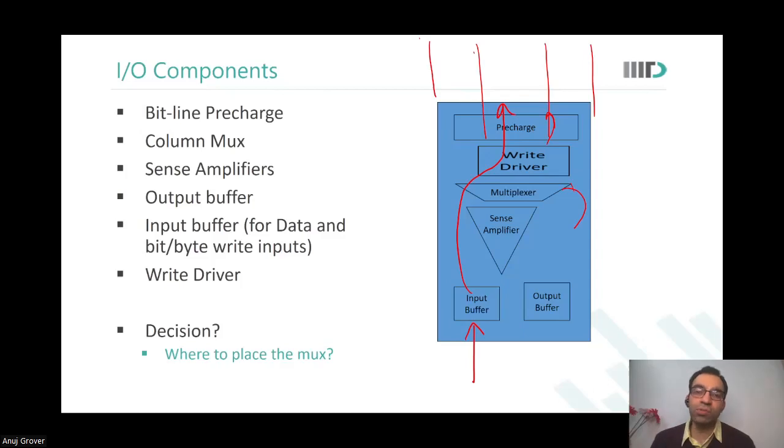So if the time to discharge the bit line to 0 has increased, what has increased? The setup time has increased. Yeah. So data setup has increased. So performance has gotten impacted, no? Yes, sir. Performance is not just cycle time. For a memory, you saw the data sheet had so many timing definitions. So that is a performance hit. You're able to see this? Yes, sir. Okay.